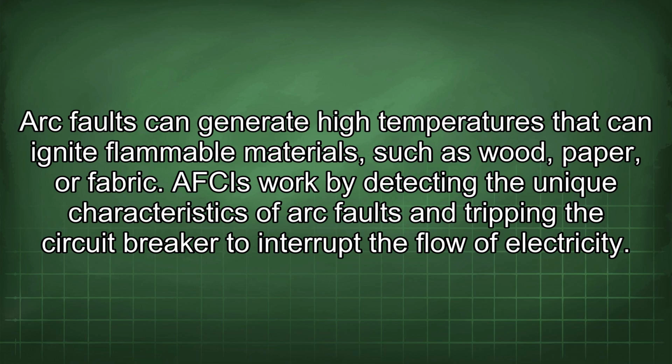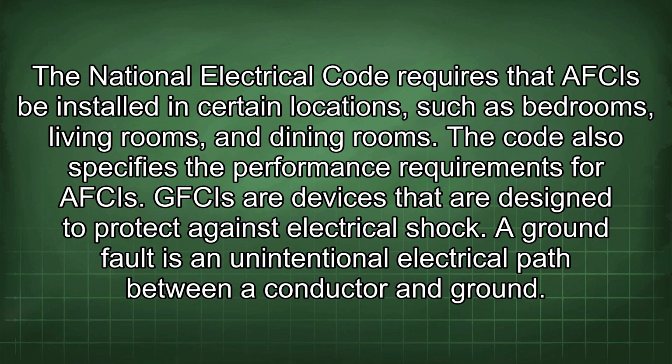AFCIs work by detecting the unique characteristics of arc faults and tripping the circuit breaker to interrupt the flow of electricity. The National Electrical Code requires that AFCIs be installed in certain locations such as bedrooms, living rooms, and dining rooms. The code also specifies the performance requirements for AFCIs.